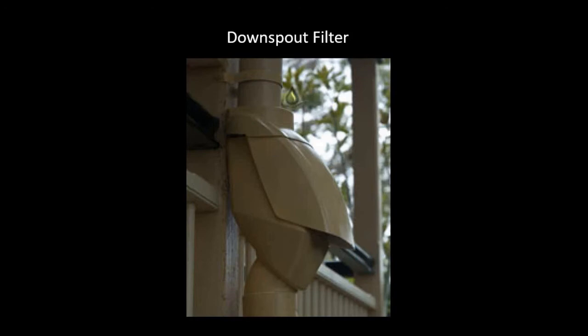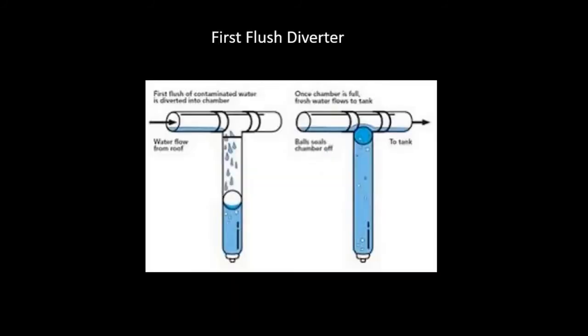There again, my personal preference is to have gutter screens, like a gutter guard. One caution about gutter covers is there is one, I think it's called a leaf guard, and it's solid metal with a curl on the end, and the water wicks down into the gutter and the leaves cascade off over the side. That's not as good a system for this purpose, because you want to capture all the water. You don't want it spilling over the edge. And so I would recommend, if you do this, that you have some kind of screen rather than something like the leaf guard approach.